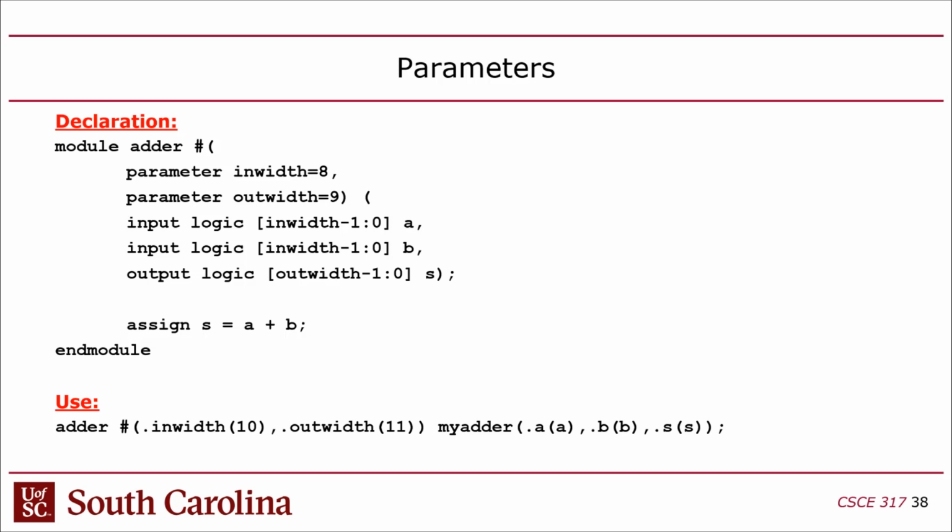But then you can customize it to define what sort of object you want to be able to put in that linked list, right? It's the same idea here with Verilog, but usually they're used for widths, most commonly, or memory sizes or something like scale. It's a way to scale up a module. So you could say, well, I want an 8-bit multiplier. Well, what if I want a 16-bit multiplier? You're going to write a whole new module? No, I just use a parameter, and then I can just set the width. I can have one parameter that'll let me generate an 8-bit multiplier or a 16-bit multiplier, right?